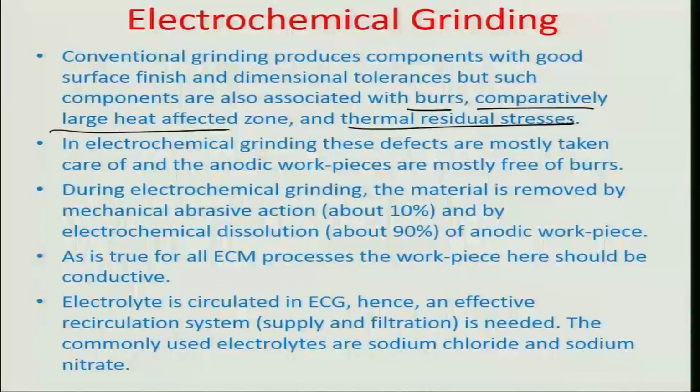So the abrasive action in an ECG process is only about 10% in terms of its contribution to the overall material removal rate. What is more important is the electrochemical dissolution part, which contributes to about 90% of the material removal. And how it happens is again the way that the ECG process is developed and the way that the wheel approaches the workpiece, okay, when such electrochemical grinding is carried out.